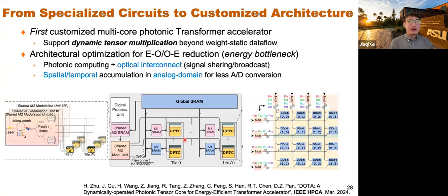In terms of the computing, photonic computing only takes a small part. For some commercial accelerators from Lightmatter, the startup company, their data shows the optical part only takes 8% in total, ADC and DAC in total take 20%, and the other digital electronics, especially data movement from memory, take over 50%. As you can see, memory is still a bottleneck. But we can use some smart design. For example, we can combine optical interconnect to at least remove the data movement cost from the electrical interconnect.